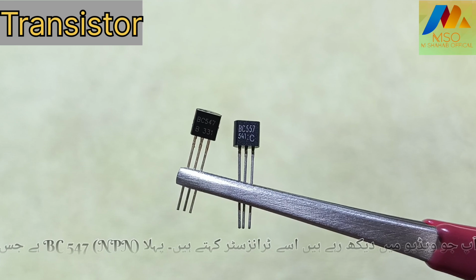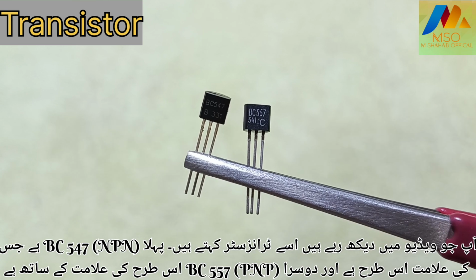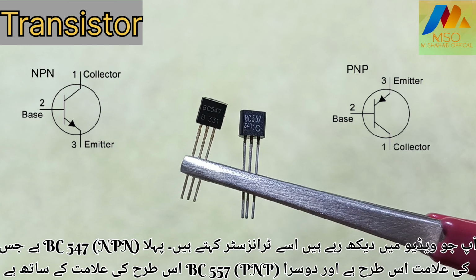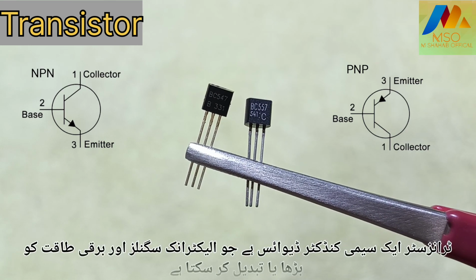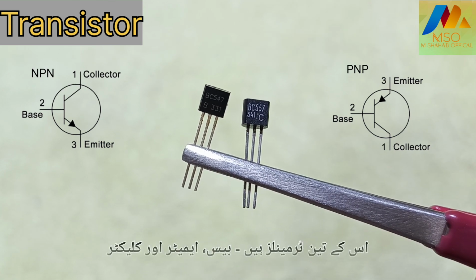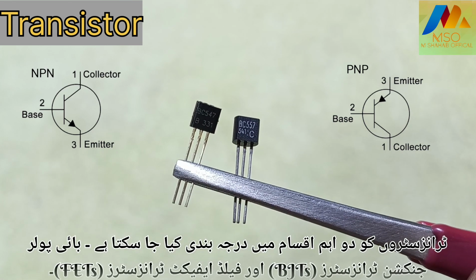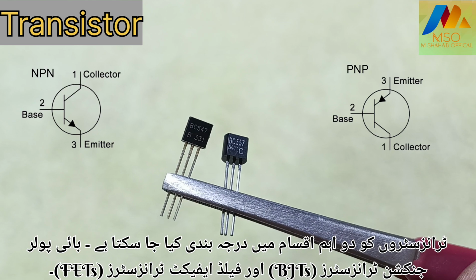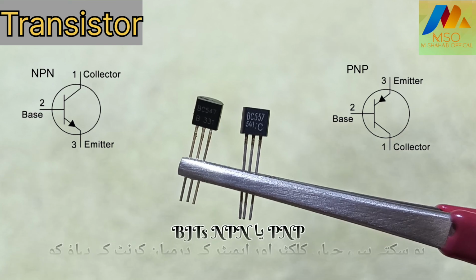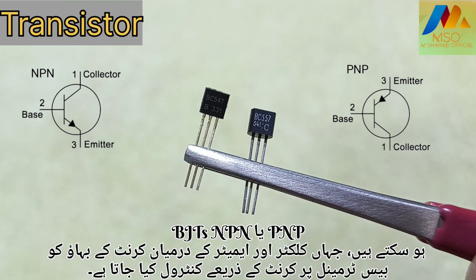Now, what you see in the video is called the transistors. The first one is BC547, NPN, with a symbol like this, and the second one is BC557, PNP, with a symbol like this. A transistor is a semiconductor device that can amplify or switch electronic signals and electrical power. It has three terminals, the base, emitter, and collector. Transistors can be categorized into two main types, bipolar junction transistors, BJTs, and field effect transistors, FETs. BJTs can be NPN or PNP, where the flow of current between the collector and emitter is controlled by the current at the base terminal.